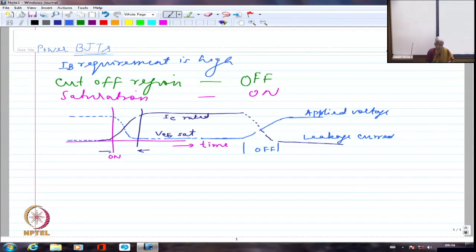That is where generally we get into loggerheads with many of the industries. The industries say that the efficiency you have calculated is not correct because you have not taken the switching losses into consideration. So the switching losses generally need to be accounted for, especially if I am talking about multiple switchings taking place during one cycle duration itself, which we will talk about eventually when we talk about inverters, rectifiers and so on. We will look at that, then we will be able to appreciate this better.